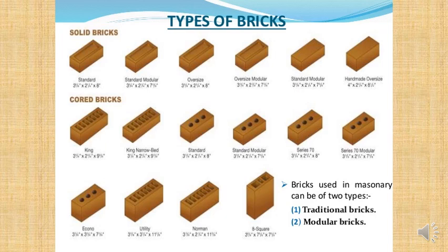Well, that will mean if it's a standard brick without any frog or without any hollows, then it's probably going to have a fairly small face, which means you're going to need more bricks in order to fill in the wall cavity. Whereas if you have a frog, or if you have a hollowed out brick, you can actually have a larger brick for a given mass. And so with that, you can actually reduce the labour, and by that the cost of the wall.